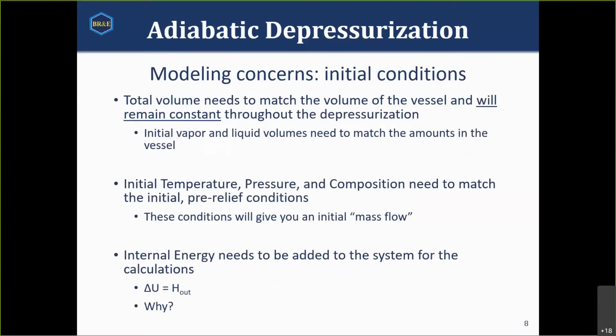When we start to model this, there are a few things we do need to be aware of. First off, the total volume of my system will always be the total volume of my vessel, or the max volume of my vessel. It will remain constant throughout my depressurization. Now, of course, are there systems where the volume of the system changes? Of course, there are bladders out there that do adjust. We are going to ignore that case for the purpose of this webinar. There are ways to get around that, but we are assuming that the volume of our vessel is constant.